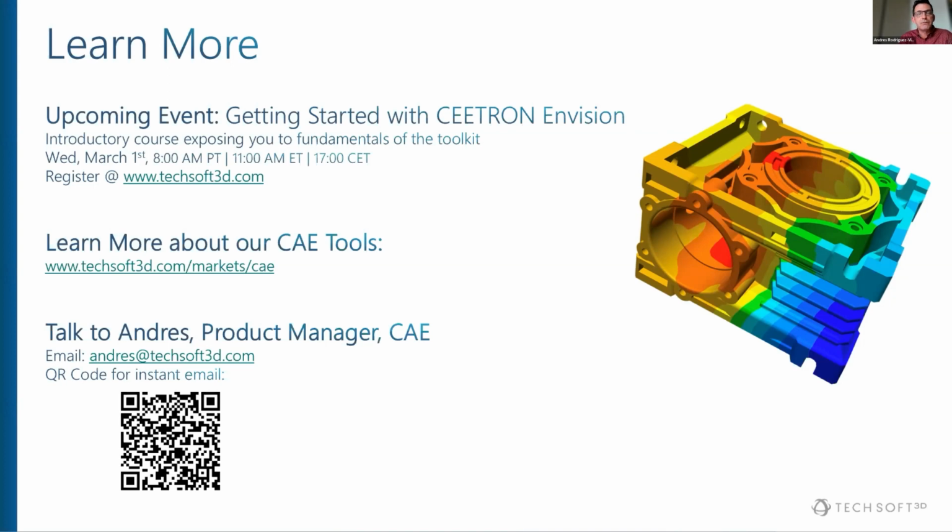Yeah, that's built in. Awesome. What about voxel meshes? We had some questions about that. Nope, that's really out of scope. The volume meshing is, as I said, TET generation and also hybrid TET pyramids to hook onto quads on the surface if needed.